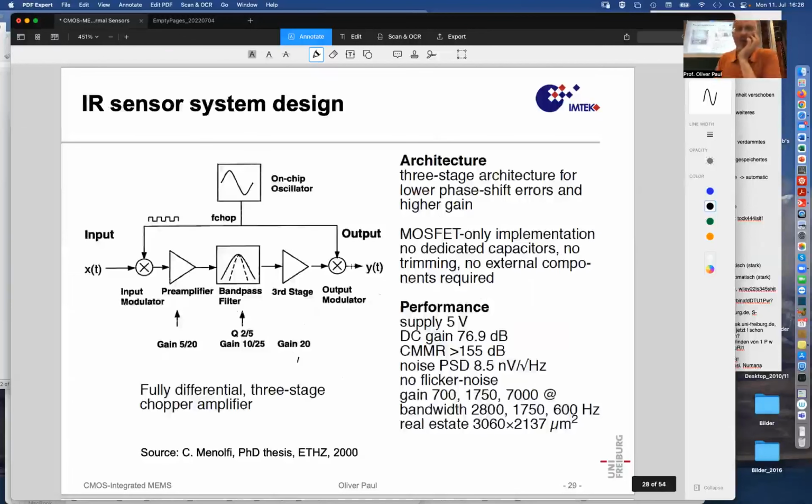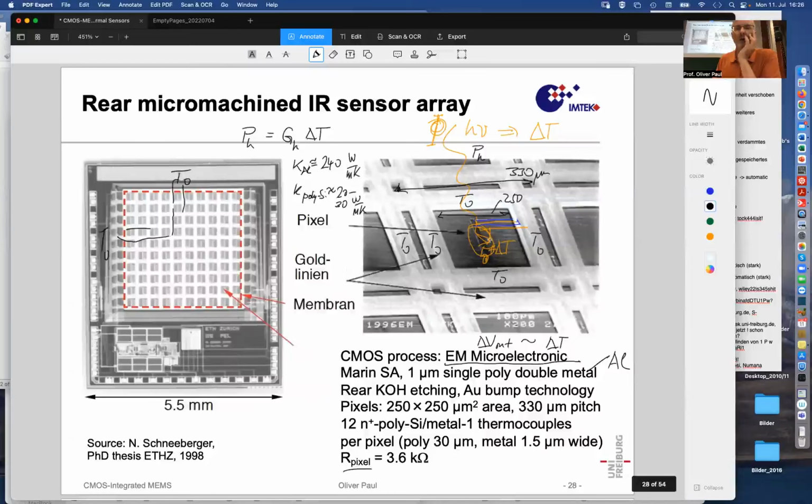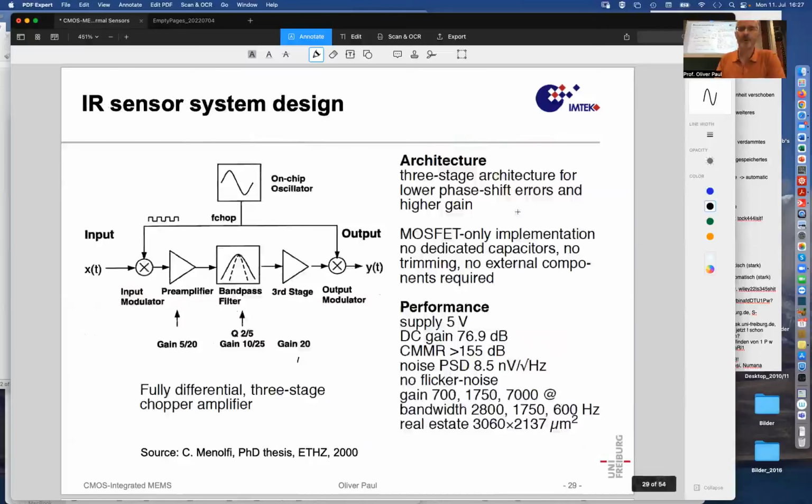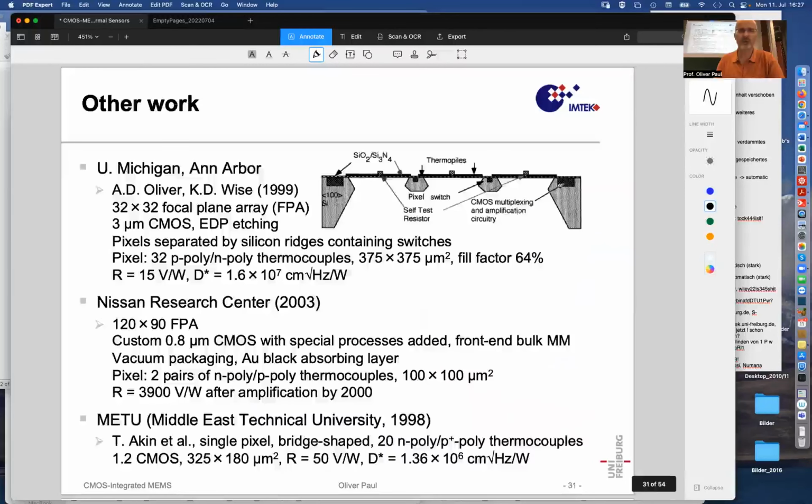You can imagine that when 1 watt of radiation power impinges on the pixel, it produces 4 volts of output signal. Of course, there is not 1 watt, there is microwatt coming in, so that microvolts of signals are coming out. And those microwatts that come in correspond to a certain temperature of the object being projected onto that pixel. So there's a noise equivalent temperature difference that can be detected, and it was a few degrees for that system.